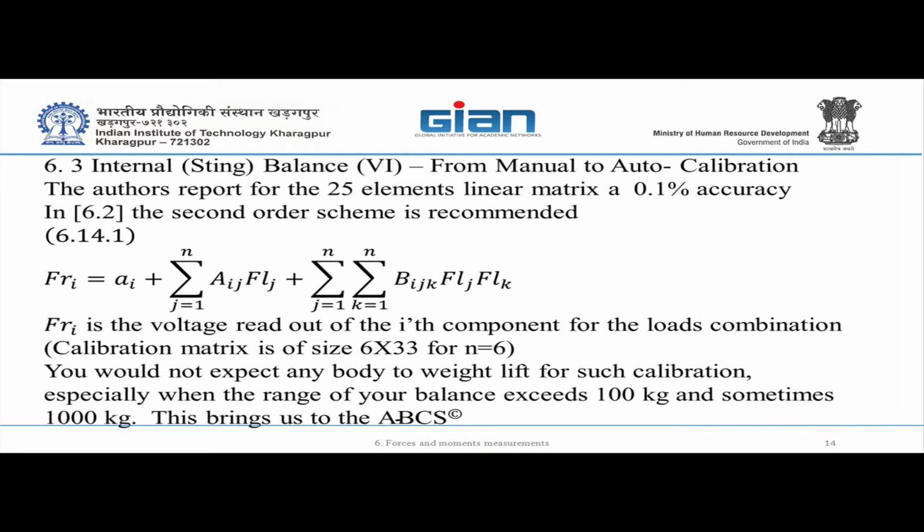Suppose you have a high capacity balance, some 200 kg. For us, it's too small. But your expected load is some 50 kg. Can I calibrate up to 50 kg and use it? Yes. For sure, it will fine-tune your calibration, because you are using a narrow range of calibration.